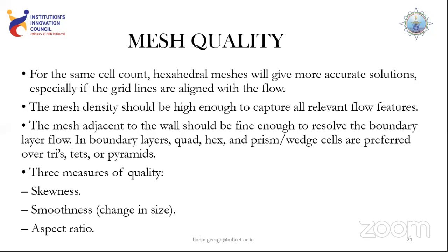And also there has to be a finite amount of mesh density. Those three are the basic fundamental aspects. However, the quality is measured with respect to these three: the first one is skewness, the second one is smoothness, and the last one is aspect ratio.